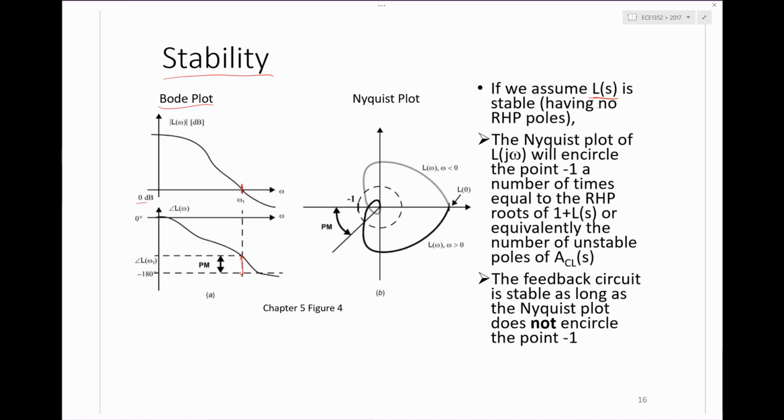So even if you're not 100% following that, it's okay, because there's enough that I mentioned there to allow you to understand the very first assumption that underlies our normal undergraduate level discussion of feedback for electronics. I said that the Nyquist plot will do some encirclements that depend on the number of zeros minus the number of poles. We always assume that the number of poles of L in the right half plane is 0.